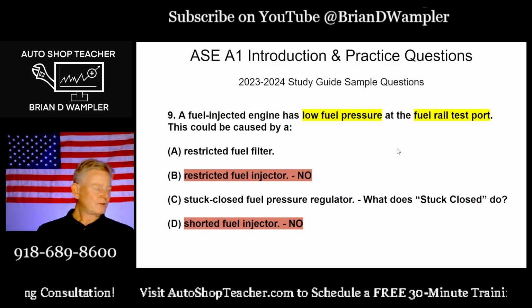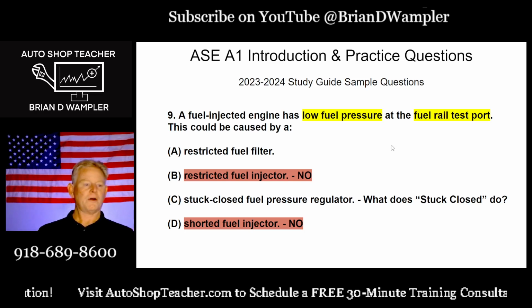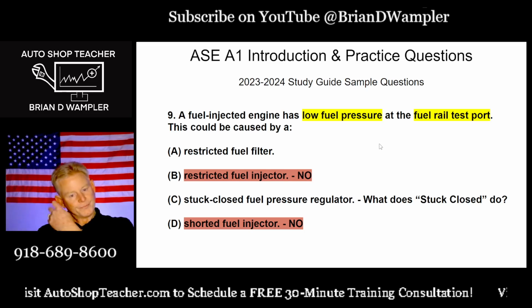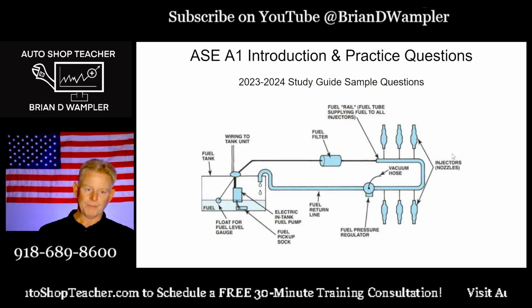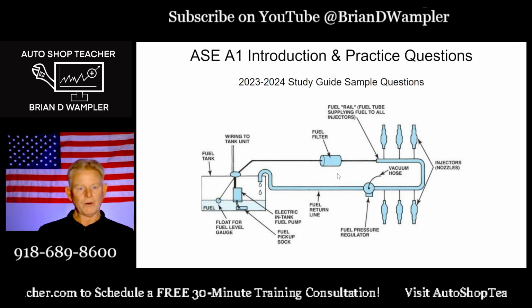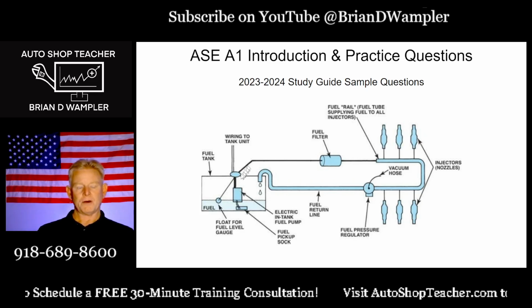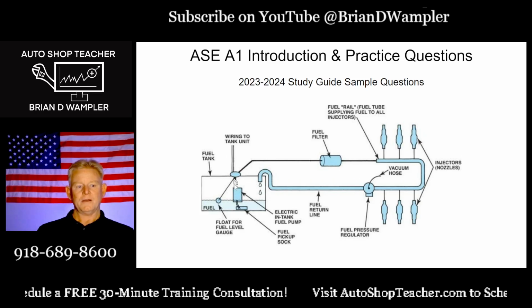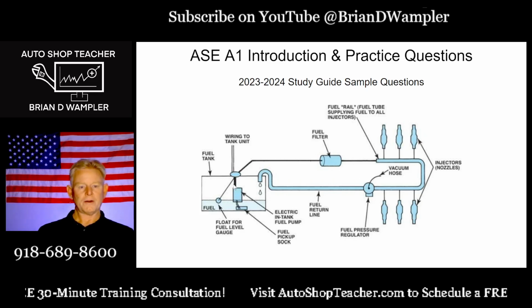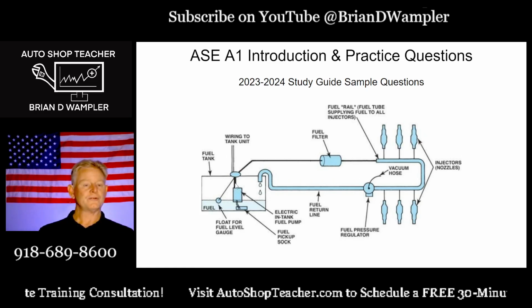Okay, so stuck closed fuel pressure regulator. If you're still debating this question, answer C is probably the one that's got you hung up on this one. So let's talk about it. Here's just a basic illustration of a fuel system, what we call a return type fuel system. So we have a fuel pump module or pump in the tank, which has wiring going to it. We know that the fuel pump is at least getting power in the question that we're trying to answer because we have fuel pressure. It's just low.